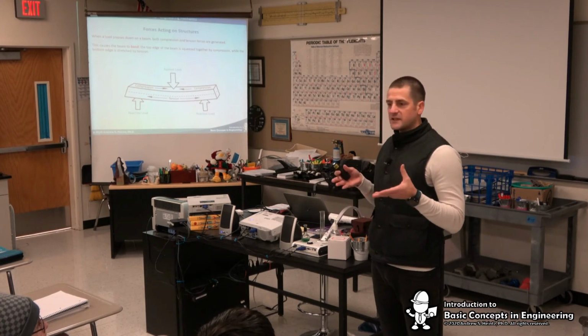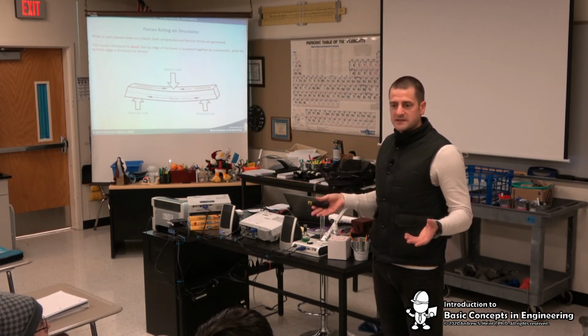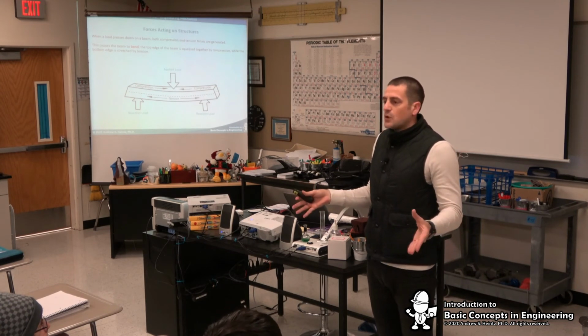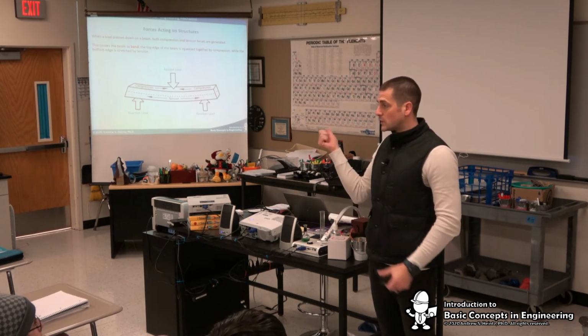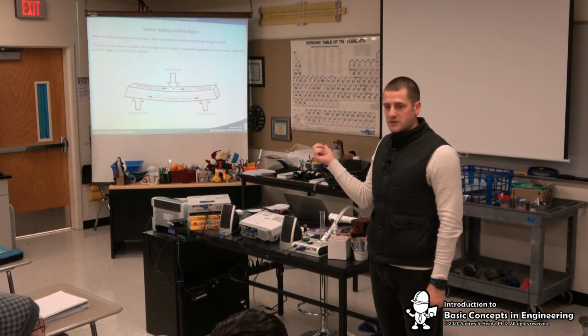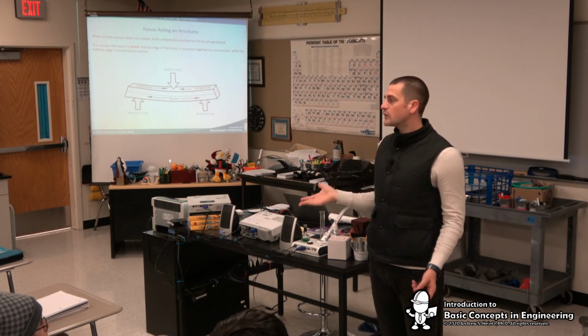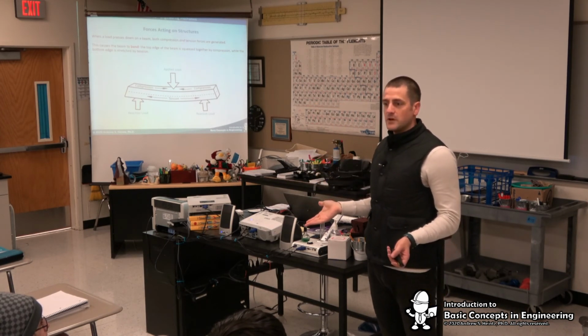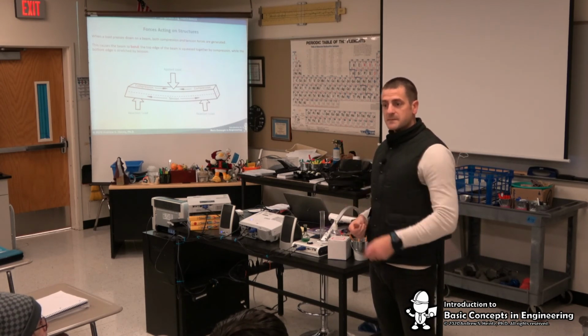But when it gets hot, it expands and starts pressing on other things. When it gets cold, it's in tension, it starts pulling in on itself. And that's why, when you're going over a bridge like the Fremont Bridge, I'm assuming you have all driven over that at some point. What do you feel when you're going over that bridge? You feel chunk, chunk, chunk. What are those chunks? Does anybody know? To allow it to. Yeah, expansion joints.